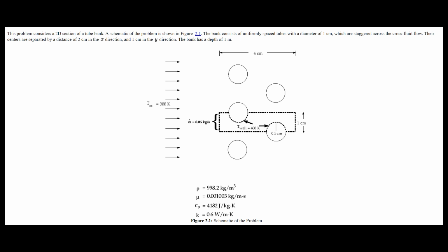Due to symmetry of the tube bank and the periodicity of the flow inherent in the tube bank geometry, only a portion of the geometry will be modeled in ANSYS Fluent with symmetry applied to the boundary conditions. The resulting mesh consists of a periodic module with symmetry. In this tutorial, the inlet boundary will be redefined as a periodic zone and the outflow boundary defined as its